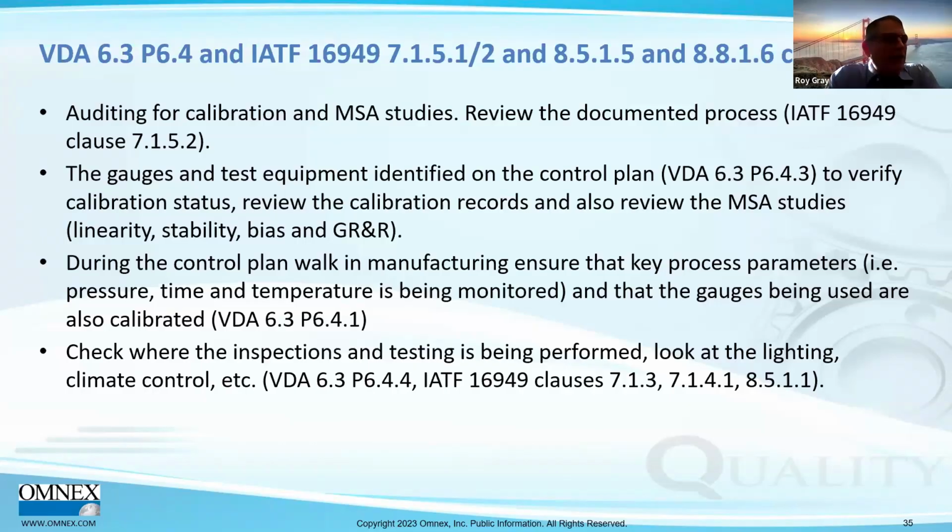If calibration verification is being done in-house, look at the internal lab scope to ensure they have that all covered and that we have qualified people to do the calibrations. Also, if they're using an outside source for calibration, that lab needs to have a lab scope. They need to be accredited to 17025.